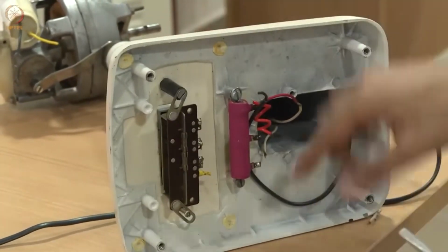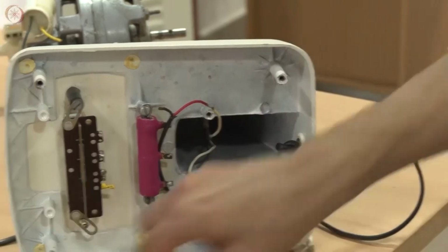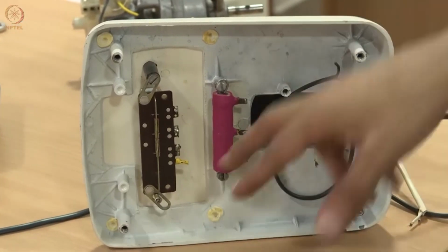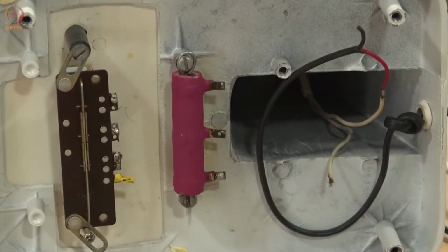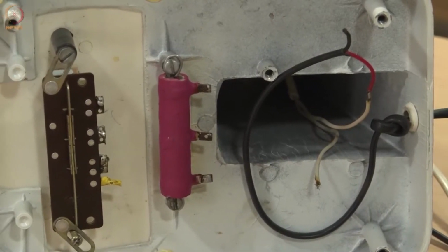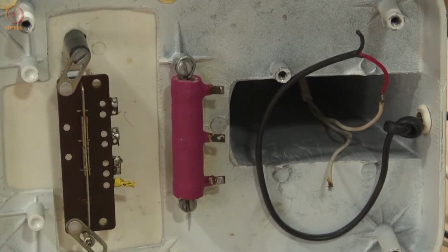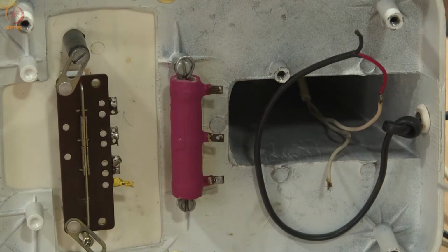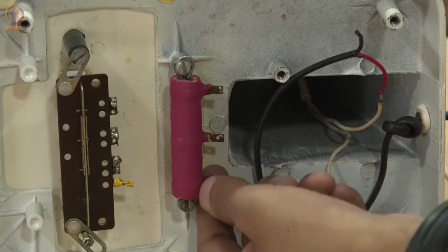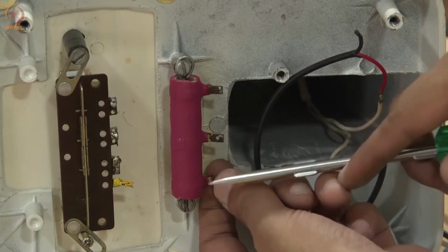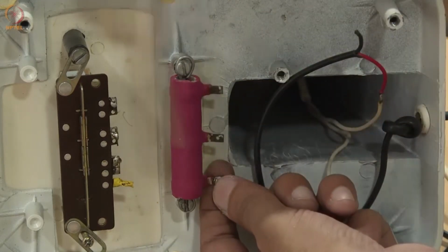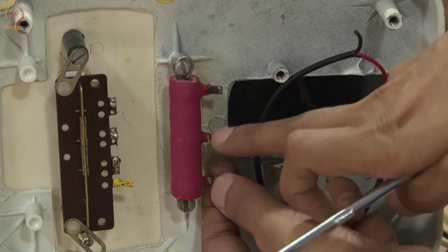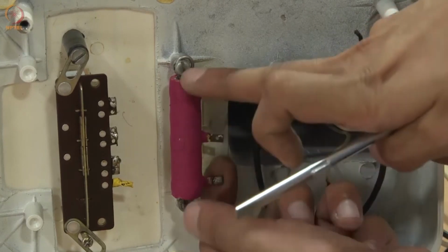Now let us just understand how this works. So basically I have a resistor here with 3 terminals. So the way this system works is like this. When you need the maximum speed of the fan, the wiring is done such that when you engage the button, the coils are directly connected to the output. So when you need to reduce the speed, you have one common terminal and there is a tapping in between. So this is one large resistance, so it's a coil basically. So I can basically tap it in the middle, or I can completely use the entire length. If I take half the length, I have half the resistance.